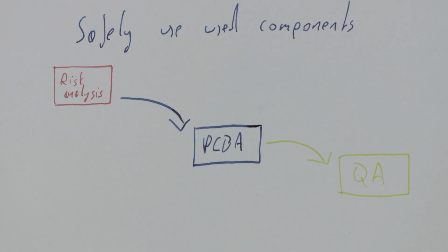And yes, finally, because some clients are just stupid and demand the use of used components to save money, there are some things which you can do to minimize the risk. First of all, of course, cover yourself contractually. And then, firstly, also perform a risk analysis. Some components, such as MEMS parts, which have moving parts inside, or sensors, are just more sensitive than, say, a transistor or something like that.